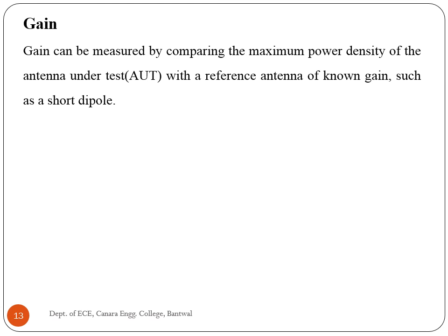The gain of an antenna is an actual or realized quantity which is less than the directivity due to ohmic losses in the antenna. In transmitting, these losses involve power fed to the antenna which is not radiated but hits the antenna structure. A mismatch in feeding the antenna can also reduce the gain. The ratio of the gain to the directivity is the antenna efficiency factor.